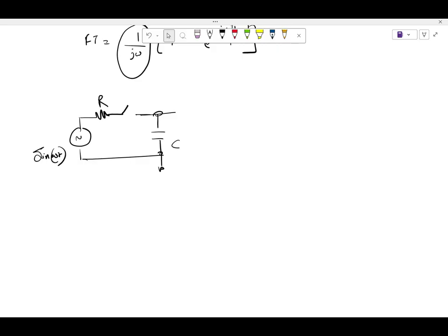So we'll apply a particular sinusoid at 0 phase to start off, and at a known frequency for the time being, and then see how it evolves. To keep it simple, we say omega equal to omega s, exactly the sampling frequency, the switching frequency of the switch.